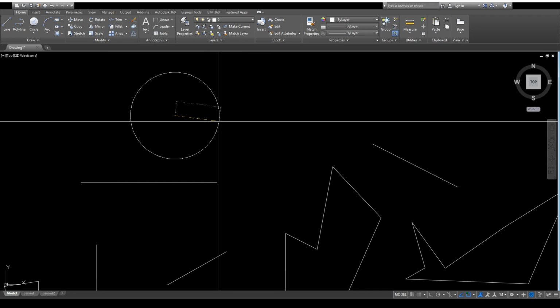specify radius of circle or diameter. I'm reading from the command bar. So, the one below, see, circle, below it says circle. Specify radius of circle or diameter. Say you want the radius, which is half of the diameter, right? So, I want the radius to be 5. Sorry, I want the diameter, for example, to be 10. So it asks what you want to specify, diameter or radius.